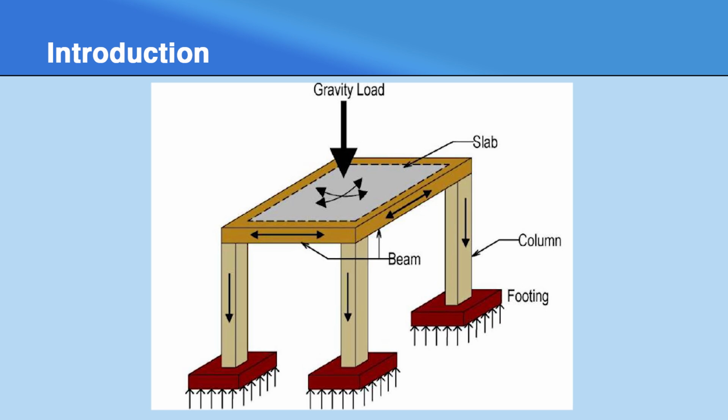When the loads are transmitted to the subsoil, it settles. If the settlement is minor and uniform throughout, the building will not be damaged. However, if the settlement is excessive or uneven, it can cause significant damage, manifesting as cracked walls, distorted doors and windows openings, cracked lintels, walls thrown out of the plumb, and sometimes even the complete collapse of the building.